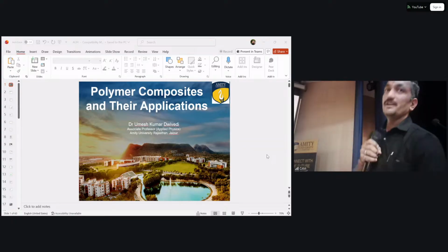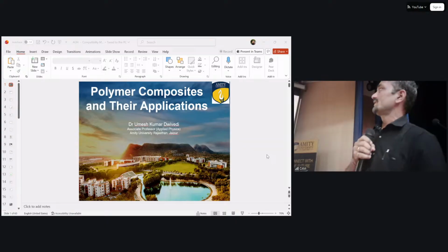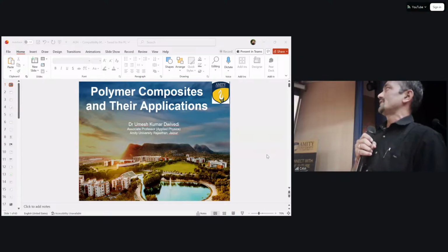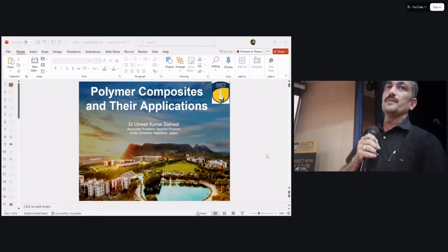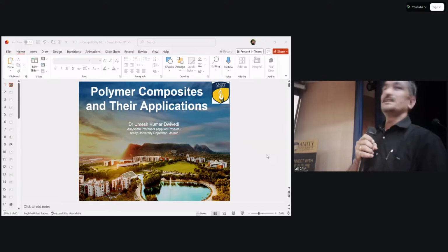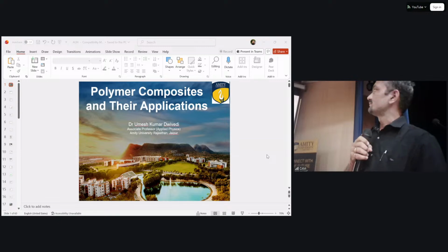But some limitations are also there. What are the limitations? Low maximum working temperature, sensitivity to radiation and moisture. Processing temperatures are generally higher than those with thermosets. Special processing equipment is required. For different polymers, we require different types of processing. That is one of the disadvantages in this area. Thermoset resins have poor impact resistance, so we should increase it, then we can use it.